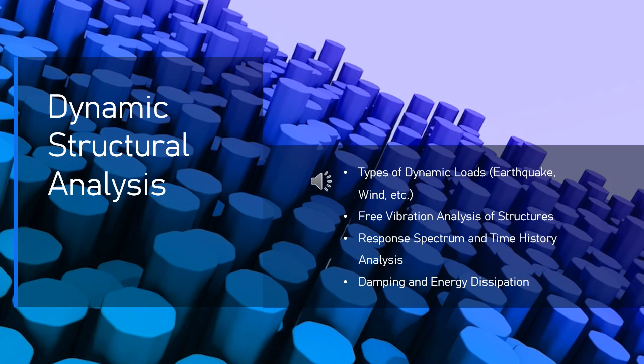9.3. Comparing response spectrum analysis and time history analysis. Characteristic. Response spectrum analysis, RSA. Time history analysis. The approach. Frequency-based, peak response of modes. Time domain. Full dynamic response over time. Computation. Less computationally intensive. More computationally intensive.